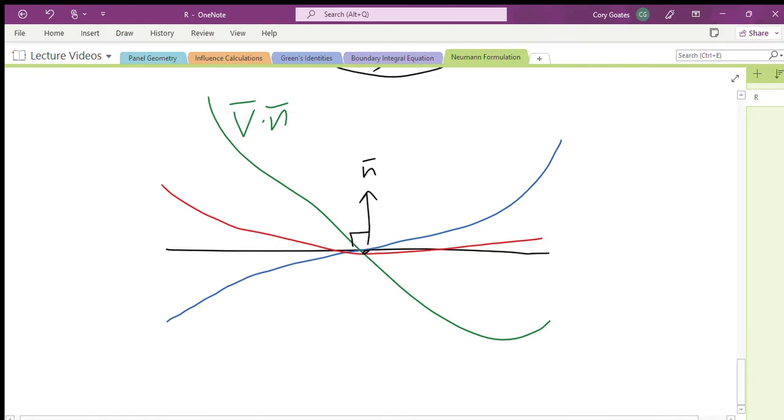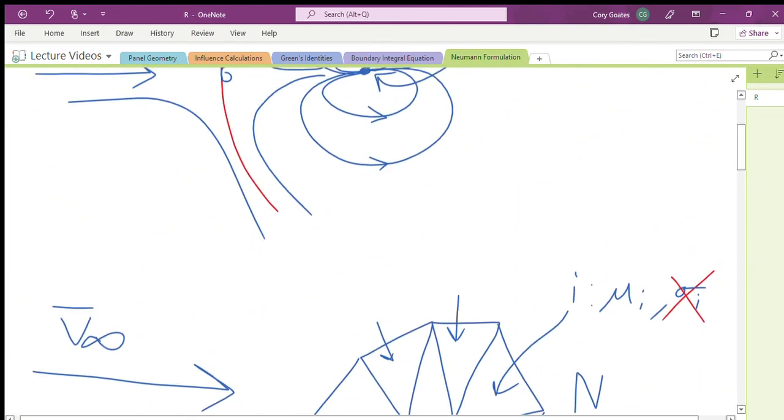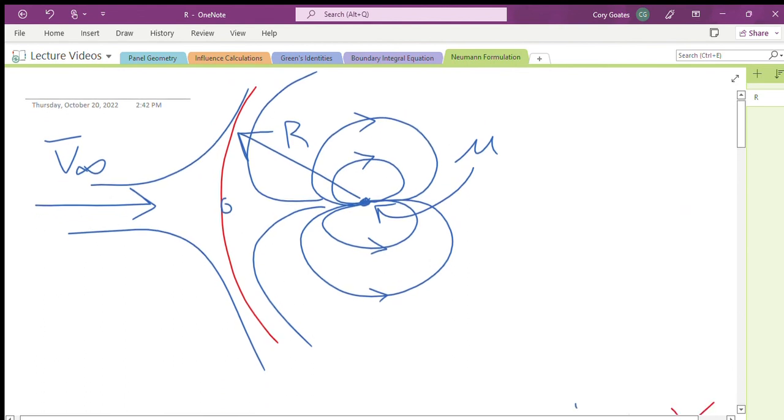Now, if you remember, going way back to up here, when we derived this relationship for a cylinder in two-dimensional flow using a free stream and a point doublet, and you'll remember we had a homework problem on this, we can show that everywhere on the surface of that cylinder, every single point, the normal velocity is exactly 0. We can show that, and that's pretty sweet.